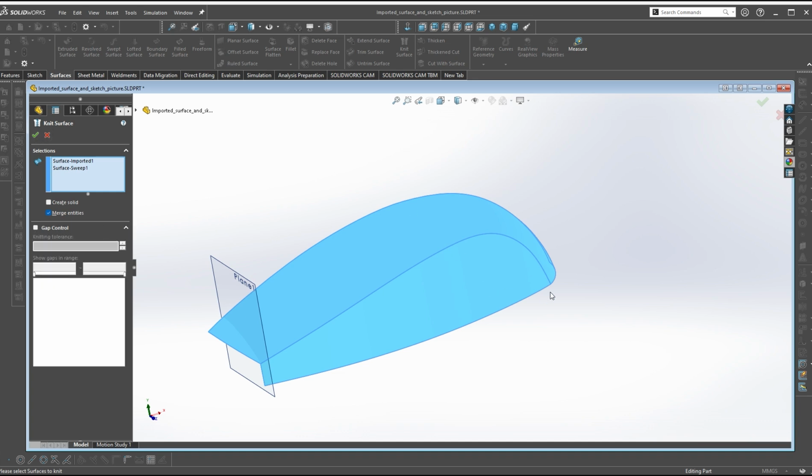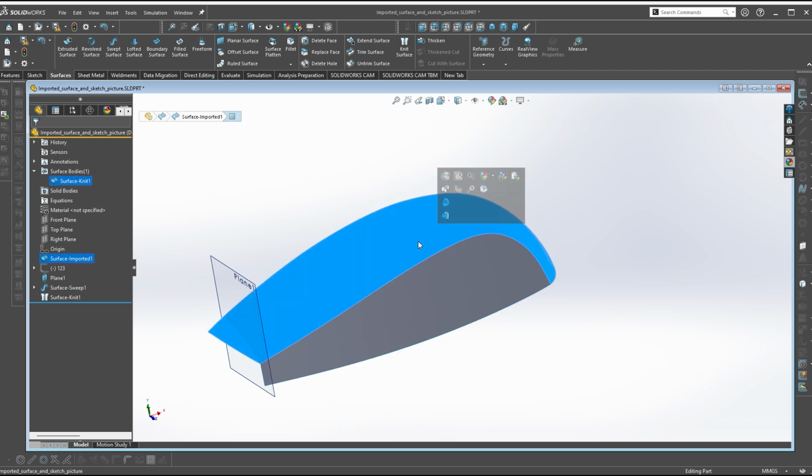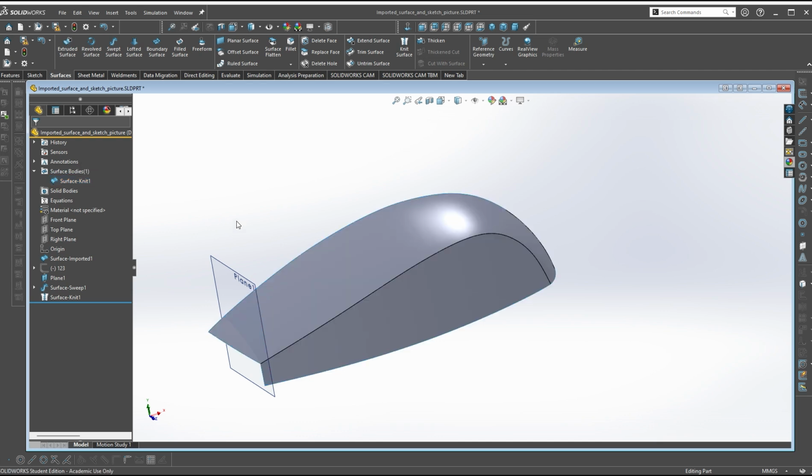And again, using those pierces as those relationships will save you a lot of frustration trying to overcome issues and gaps that happen if you're not using the right kind of surface technique, or if you're not using pierces to create relationships. So let's do this, and then you notice something. It creates one surface. In fact, if you click on it, you can see the different surfaces are addressable. But now you've got this surface net.